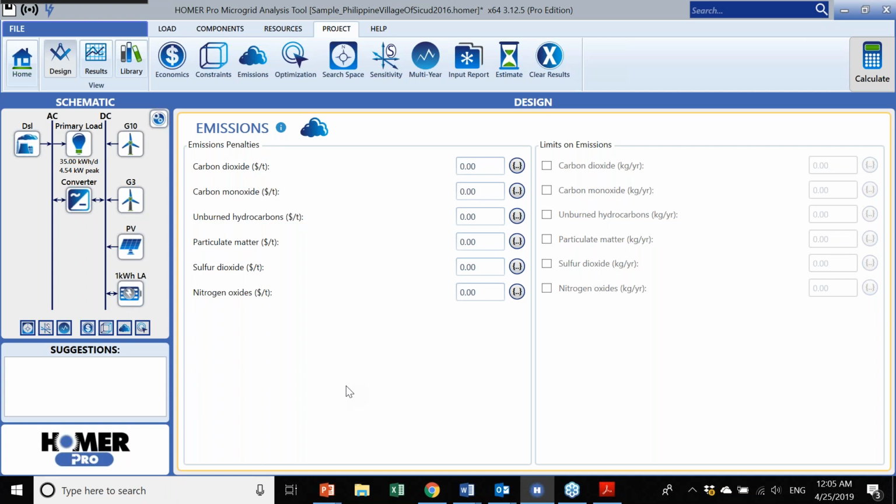Okay, so Homer calculates that automatically, so you don't have to account for it. We look at the initial investment of the component, and then we depreciate it over time. So there's the initial capital cost, and then throughout the life of its design, we take account of the lowering operating costs. So when it gets to zero, it still has life in there. Then it's reflected in the actual cost of the system. So we do that already. But when it comes to the sensitivities, everywhere through the software, you see these little circles with little brackets. These are your sensitivity calculations.